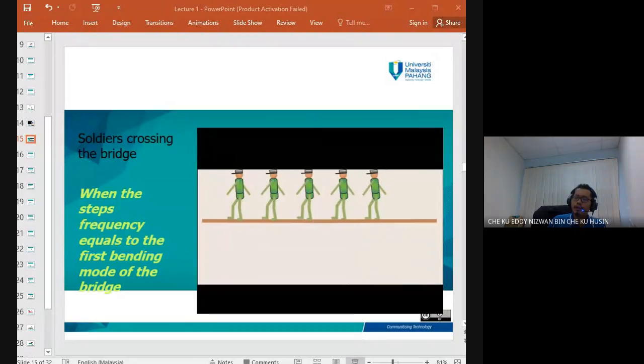This kind of technique has also been applied to find the natural frequency of huge structures. Normally the common practice is to use an impact hammer to induce force, but with a very huge structure it's not easy to give a sufficient amount of force to excite all the natural frequencies.